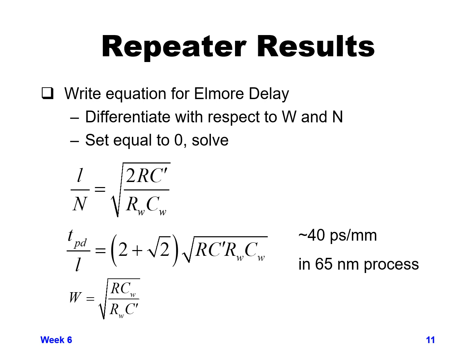And then you can do some simulations where you vary the distance and find an ideal distance that you drive based on the metal layer that you're in and the repeater size that you're using. And then you just place a repeater every X amount of distance that you determine as your ideal distance. So generally I don't use the equations to figure out an ideal number of repeaters for a given distance, but try to figure out the ideal distance between repeaters for a given process technology and metal layer.